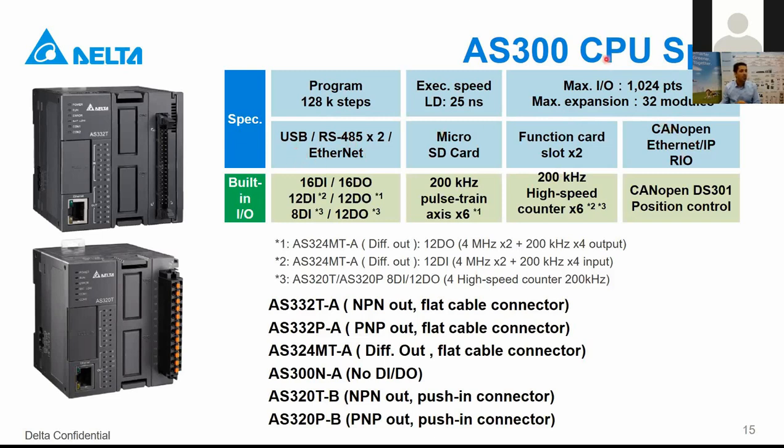So for the AS300, CANopen and Ethernet IP and also Profinet allow us to make a remote I/O solution. I will show it to you, and we will talk about it as well. So here, what I want to mention, CANopen supports CANopen DS301 position control standard. So you can use the CPU as a CANopen master to control CANopen slave devices.